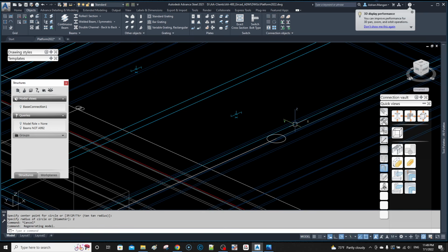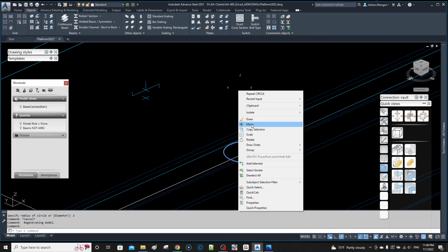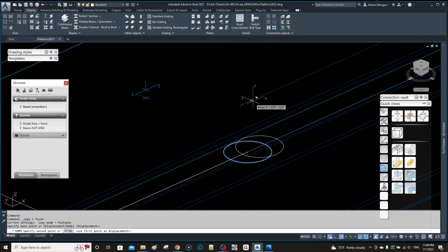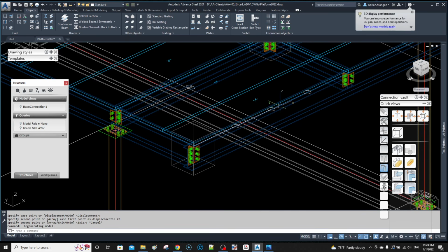I'm going to make the stairs 4 feet wide, and then the handrail I'll put on top of the stringer, in the center. So then I'll move another post over 4 inches. What I'm going to do is 2'4" either side. So I'll just copy this over, 2'4" or 28 inches, which is 2 keystrokes instead of 3. So that's where my handrail is going to start.